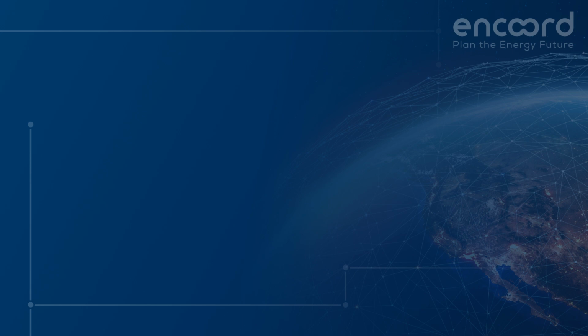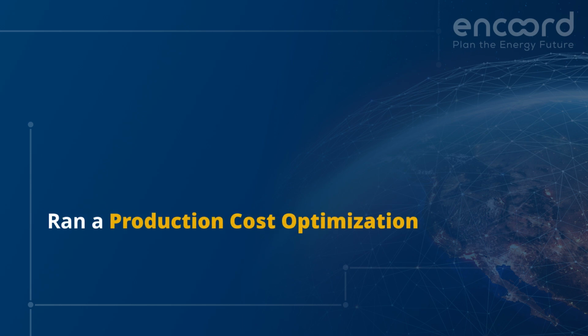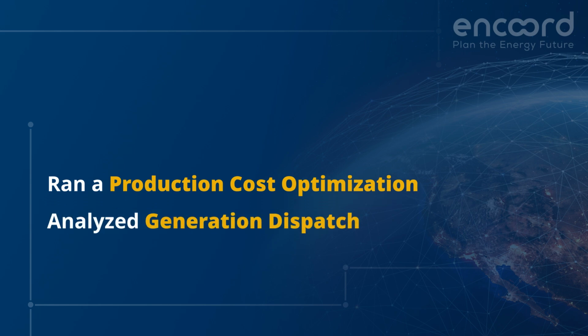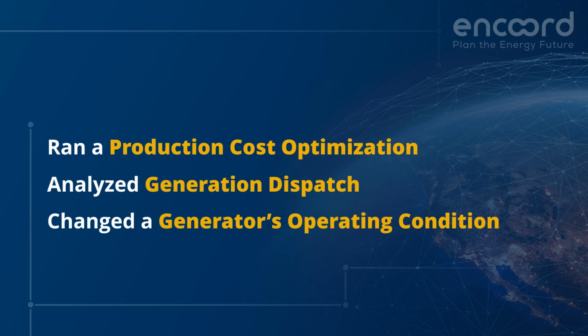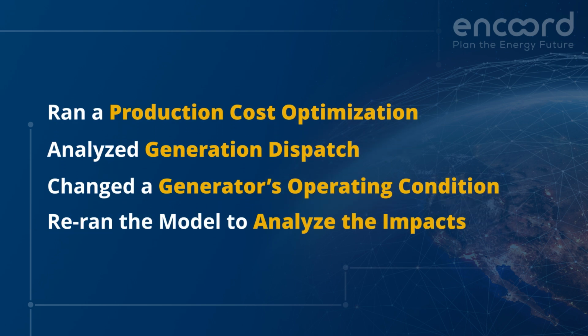In this video, we ran a production cost optimization for 1 week, analyzed generation dispatch, changed a generator's operating condition, and reran the model to analyze the impacts.